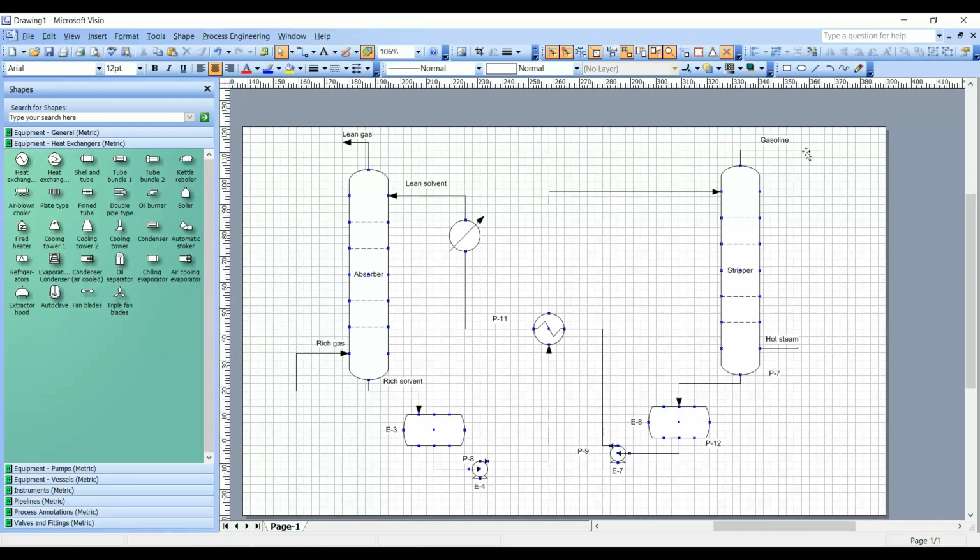Because this is the main product that we're interested in, in many cases, or in every case, you would find people having one vessel like this. I'm again copying. Just press Ctrl while you are dragging, and it will automatically copy. People would collect it here, or because it's a gas, first you have to cool it. Then you can have a copy of this, again the same thing. Connect it here, then get one more connector from here to here, and then take this as the final product.